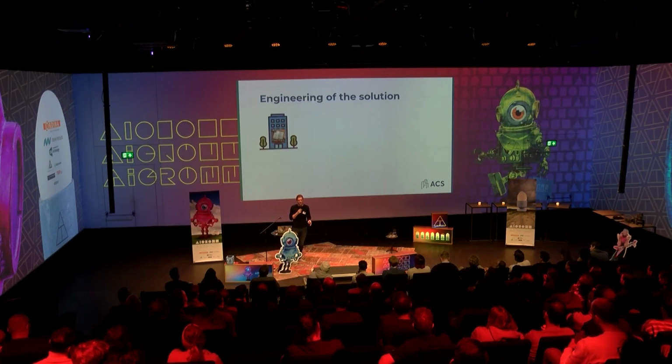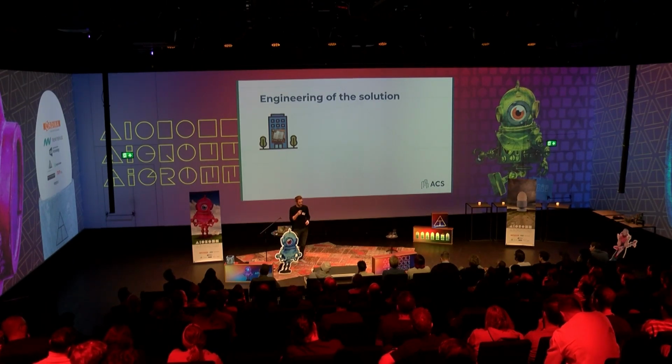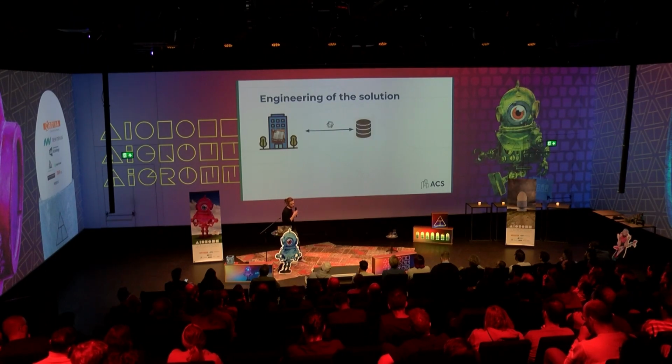So another use case, which wasn't needed for the one that I just explained, is one that calculates optimal set points. How hot does a boiler need to be, how much hot water does it need to produce right now? In that case, we want to load a trained ONNX model onto the building itself, because our controls will run locally. If the internet dies or something, you want the building to continue running. So we run our models locally. We load the ONNX model from the same database onto the building, and we use it in the control. Our control software is written in Golang.